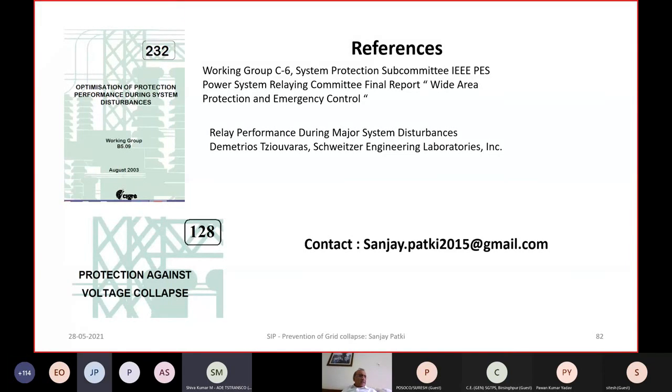Yes, you are right. Actually, that is one of the reasons why it is not desirable to trip in zone 1, because the main consideration here is that when your impedance locus is nearing zone 1, you are actually close to 180-degree opposite phases as far as the swing voltages are concerned. So at that point, opening of the breaker always carries a risk of internal restrikes, or even breaker pole failure can take place. So zone 1 tripping is actually not really desirable.